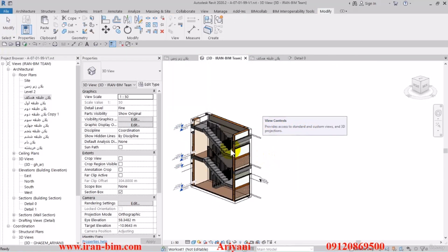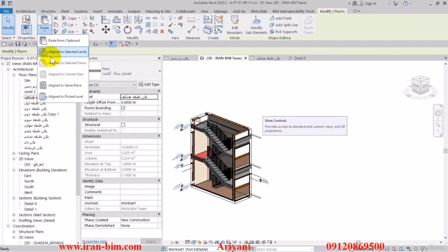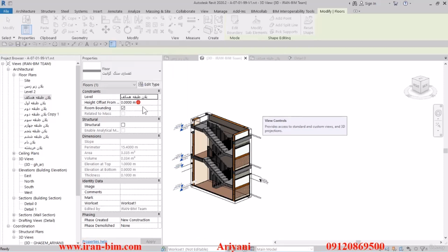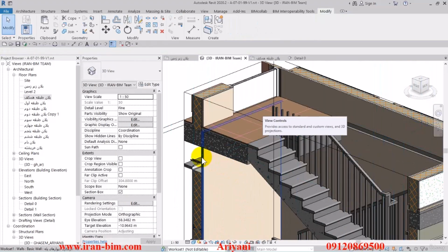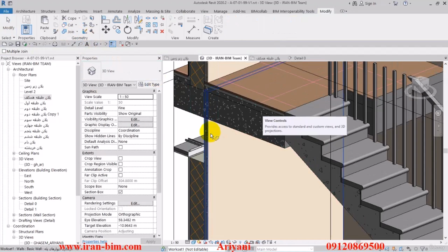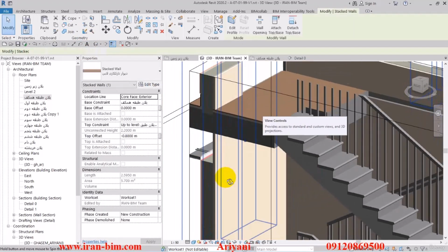and then I'll copy this floor that we have made here, and then from this menu I'll click on align to set level, and then I'll select the first floor plan. Alright, and then these parts you can join later on as well. Just try to do them as late as possible so there won't be any changes and issues popping up.